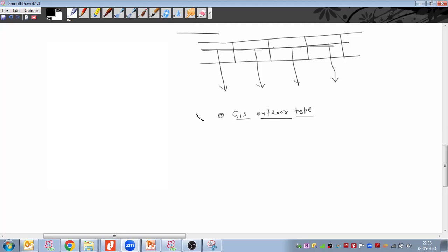It is regarding the arrangement of the bus. We can put RYB in vertical, and sometimes RYB in horizontal way also. But in the line way, it is essential to put RYB in vertical way, if two lines are one below the other. No, I don't think so. Any kind of orientation, horizontal or vertical, can be placed. Mechanical stability is achieved, so it could be horizontal or vertical. It all depends on the maintenance point of view.